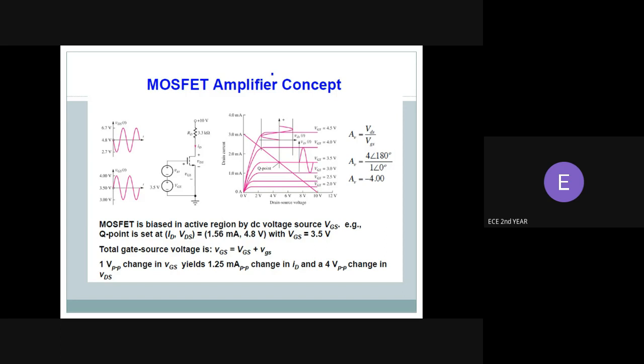The amount of drain current flowing through this N-channel therefore depends on the gate-source voltage. One measurement we can take using a MOSFET is the transfer characteristics, which show the I-V relationship between drain current and the gate-source voltage. Also, for the N-channel E-MOSFET, the I-V characteristics: with a fixed drain-source voltage applied across the E-MOSFET, we can plot the values of the drain current ID with the varying values of VGS to obtain the MOSFET's DC characteristics.